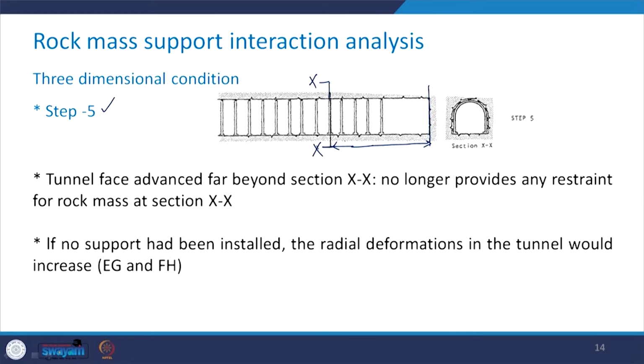So this tunnel face, which is advanced far beyond the section XX, no longer provides any restraint for the rock mass at the section XX. So whatever restraint was there because of the presence of the tunnel face is no more available at the section XX, because the tunnel face is much farther from the section XX.